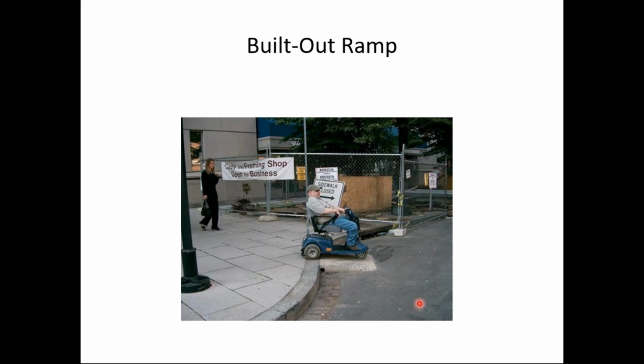But I think it illustrates one of the things about ADA, which is we have to keep an open mind, because sometimes things that we would say, I don't want to use those in a permanent setting, and that would be good advice, but they may have applicability in a temporary situation. And I think that's the case here. I too am not a proponent of built-out ramps. I suggest people don't use them. But in this temporary application, this will probably be here maybe a couple or 3 months, and there's no vehicular traffic here. I think this is probably an okay use of a built-out ramp.